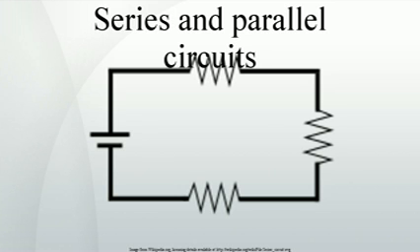Inductors. Inductors follow the same law, in that the total inductance of non-coupled inductors in parallel is equal to the reciprocal of the sum of the reciprocals of their individual inductances. If the inductors are situated in each other's magnetic fields, this approach is invalid due to mutual inductance.